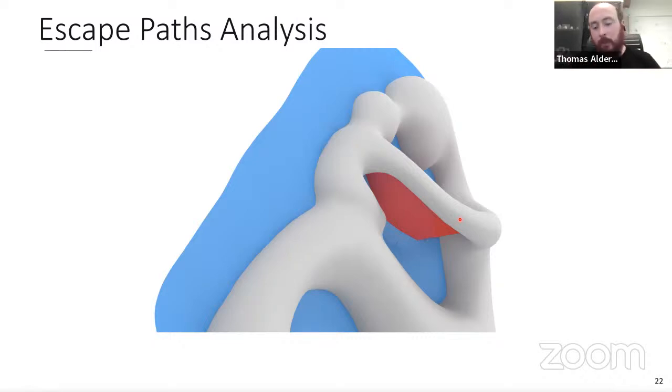Because if you are able to really fabricate very thin membranes in your geometry, then the gap will be very small, and also the silicon mold tends to stick together during the casting procedure, so that very few amount of resin would spill inside these gaps. So actually, when your cast comes out of your mold, it will have some membranes, depending on the casting material, that you need to remove and that you need to polish afterwards.